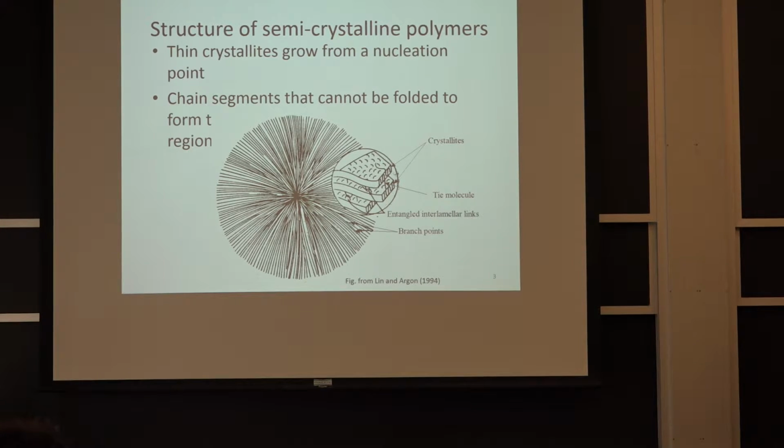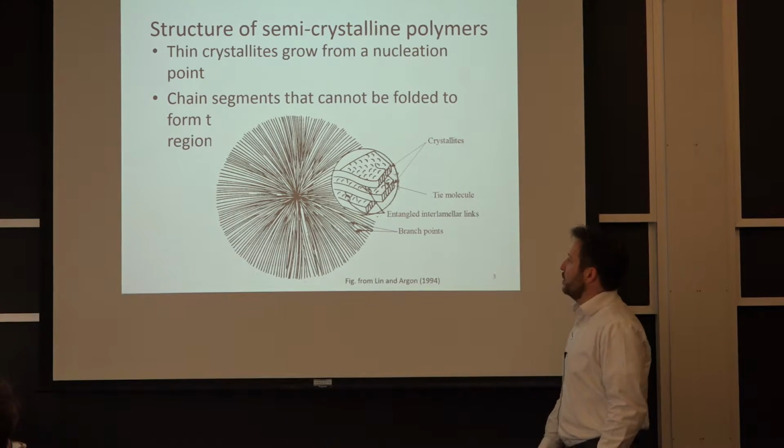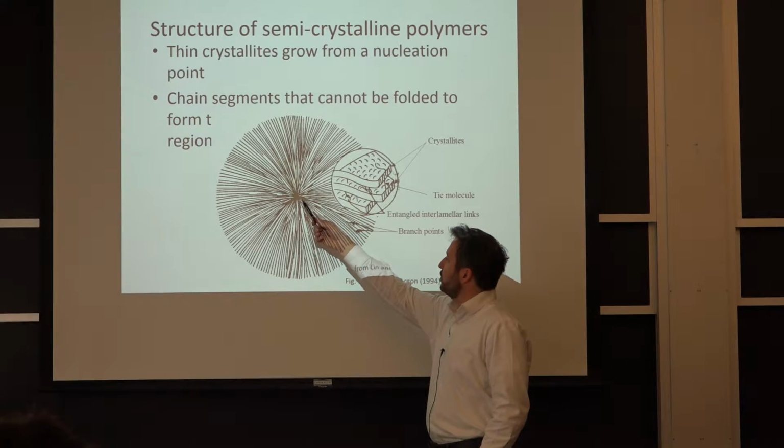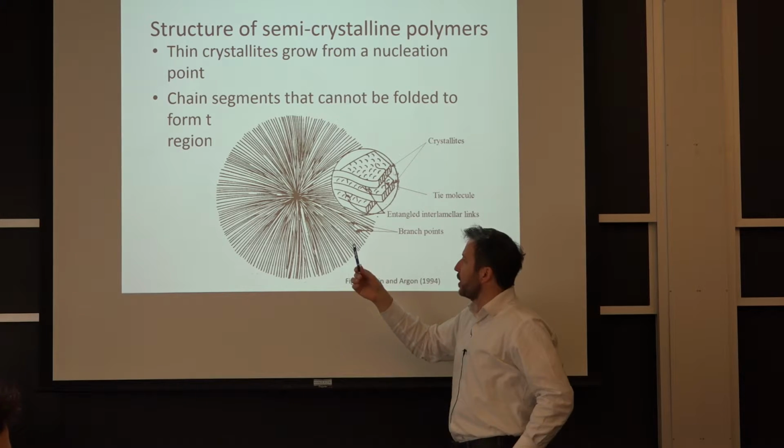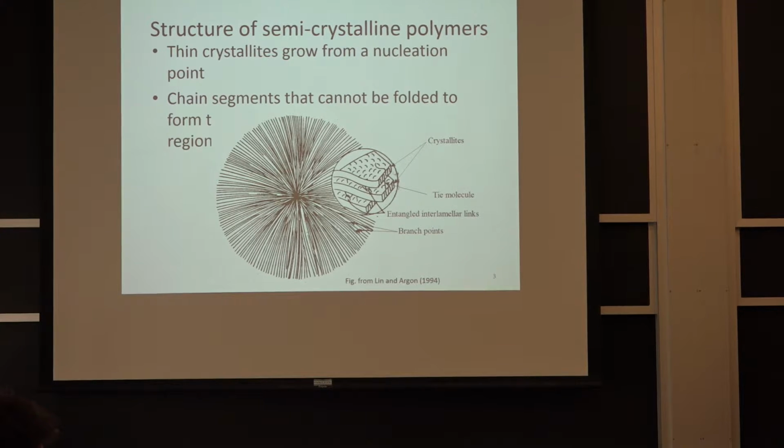So again, with respect to the polymers, some of the things we discussed last week was most of them are semi-crystalline. So we think of polymers as these macromolecules, except that for most of them, except polycarbonate, for example, and the transparent ones, they have very small crystal lamella in them, and it's organized a little bit like an ice formation, where the crystal portions form a nucleus, and they emerge in all directions. And then you have the crystals and the polymer stacked together. So essentially, it's very hard to take these big chains and organize them in a perfect way by folding them. So whatever leftovers end up between the crystals.